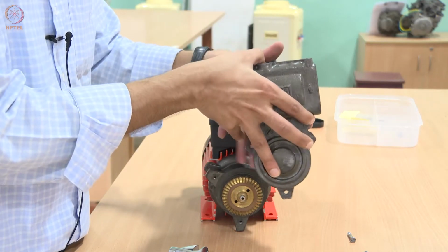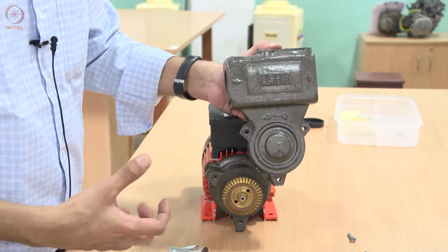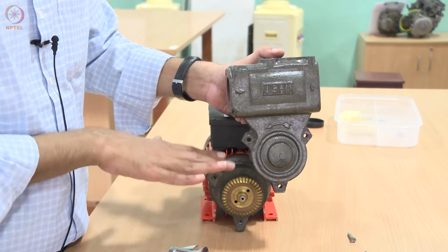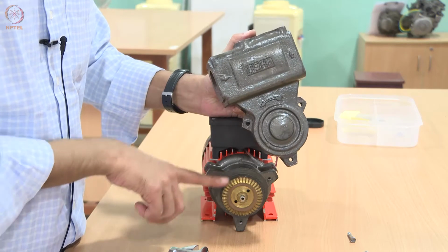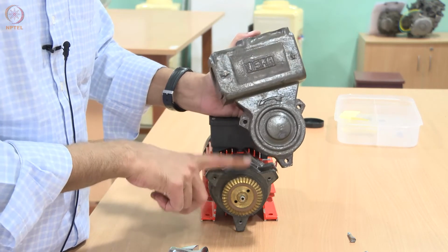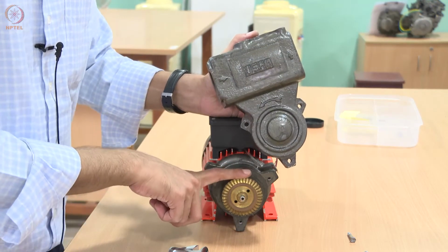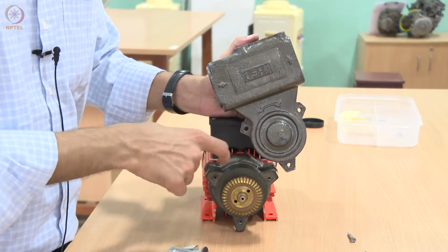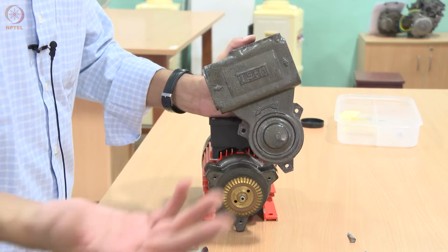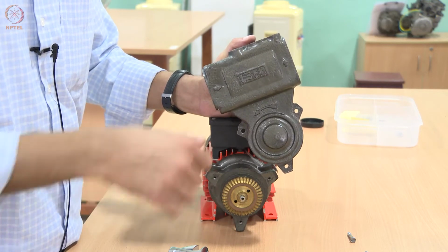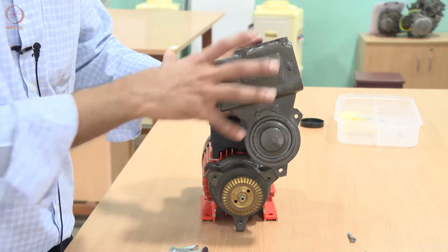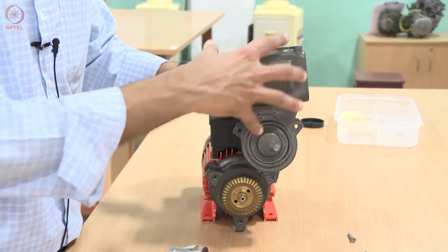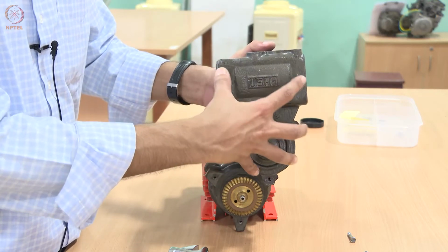Once the entire suction is fully drained of all the air, and it is filled with water, the pump has now primed itself. That's why we call it a self-priming pump. In the case of a centrifugal pump, depending on the length and volume of the suction line, you may have to fill something like 15-20 liters of water, depending on how long it is. In this case, because of the design, it requires just a very little quantity of water